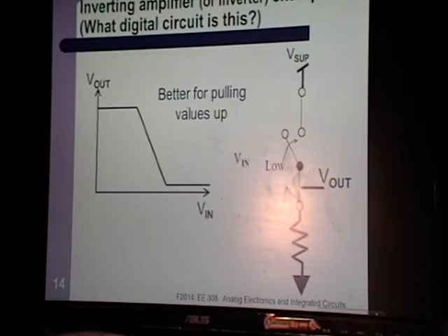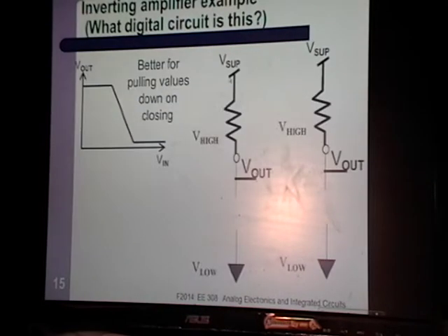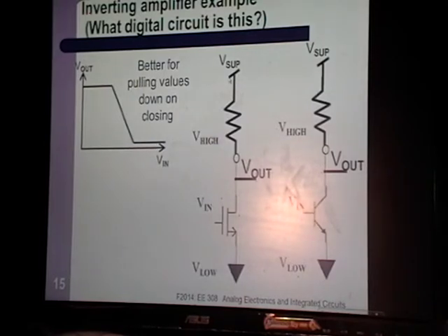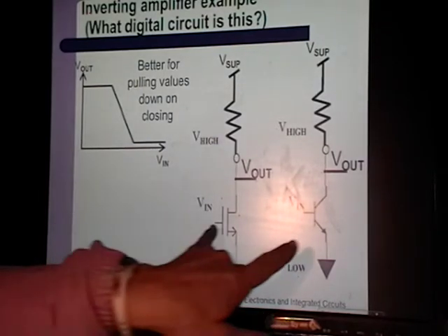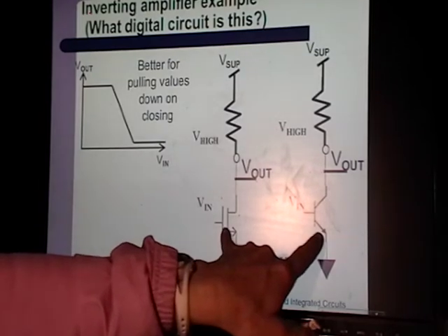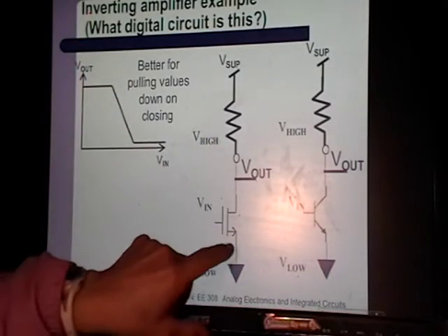Same circuit. Turns out that transistors, these circuits are naturally inverting. So even if you flip your amplifier, now since we're in analog land, I'm calling it an amplifier now, but you could call it an inverter. It's going to be the same graph as the previous slide, whether you have the switch down here or the switch up here. Okay, and so that's the end device version that we saw, and you've had practice flipping the circuits.